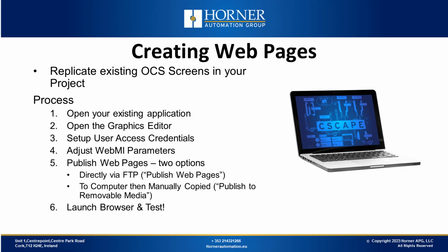The general process is to open the application, open the graphics editor, set up user credentials, adjust WebMI parameters, and then publish the web pages. There are two ways to transfer the web pages once they're created: directly over FTP or to your computer, where they can be manually copied to your SD card. The last step is to launch a browser and test it.